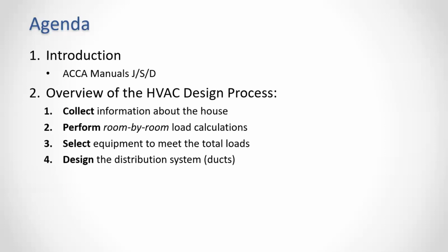Most contractors, and it's human nature, just want to oversize. They guess, they think bigger is better. They think bigger is safer. And I have tons and tons of data that proves otherwise. There are a lot of very important reasons not to oversize equipment. So if you don't know what the house needs, how do you know whether you're oversized or undersized? So you've got to do that first. And then you select your equipment based on those load calculations. And then assuming it's a ducted system, you need to design the ducts. And airflow is super, super important, especially for heat pumps. Next slide, please.